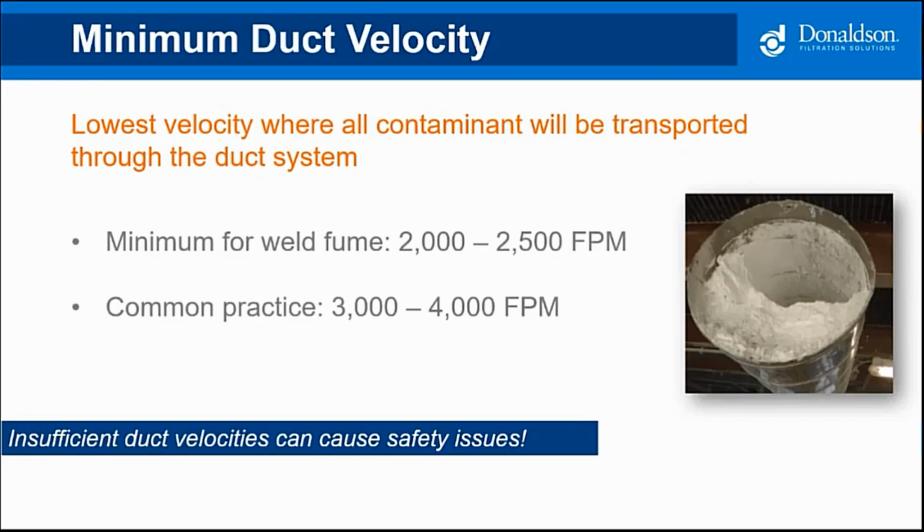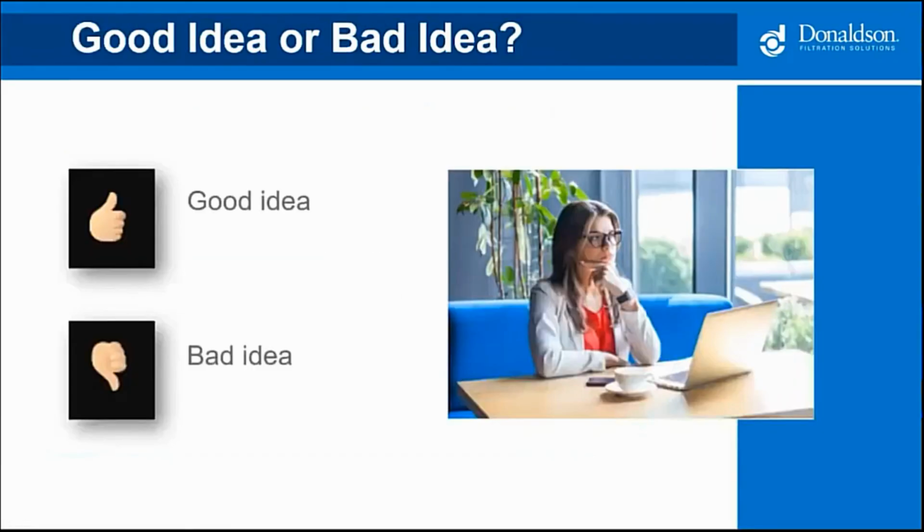The dust collecting in the duct to the right, as you see here, this is not a weld fume application. A weld fume is a very light loading, which we will talk about here in a moment. But this is a dramatization of what you're seeing. If the conveying velocities drop below 2,000, you will see dust build up in this ductwork, okay? The NFPA guidelines, if you're dealing with a combustible dust, says no more than 1/32 of an inch layer of dust in the duct, on the duct, in the rafters. So we've got to make sure our transport velocities are designed correctly.